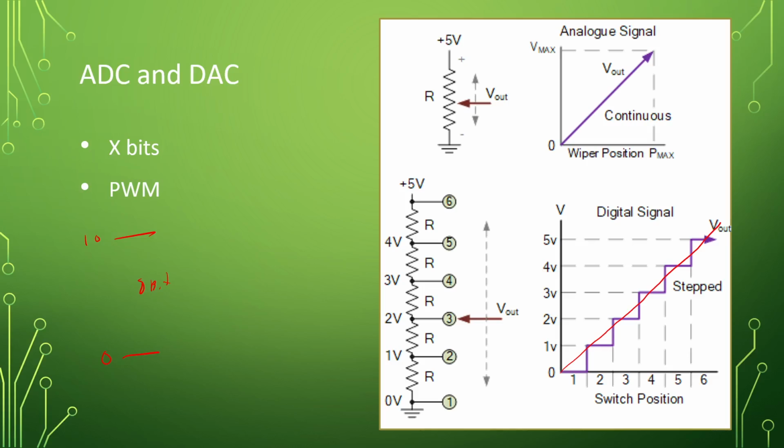So that would be 0.039 volts per step. That is the smallest deviation of change that you can accept, 0.039, which seems like a lot between 0 and 10 volts, right? Now let's just make our lives really simple. If your temperature sensor outputs a signal between 0 and 10 volts, because that's how it's rated, but it can measure between 0 degrees Fahrenheit and 256 degrees Fahrenheit, you have 1 degree of resolution. So you can only detect a 1 degree temperature change.